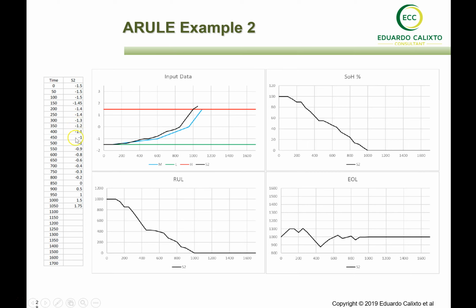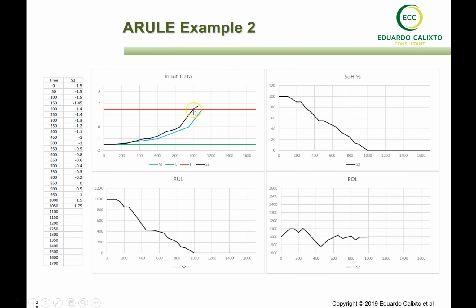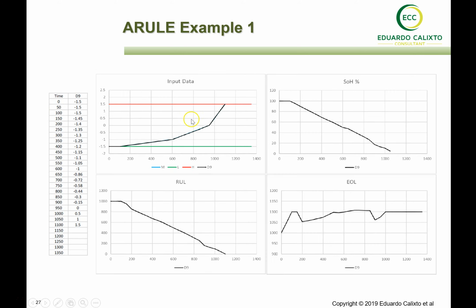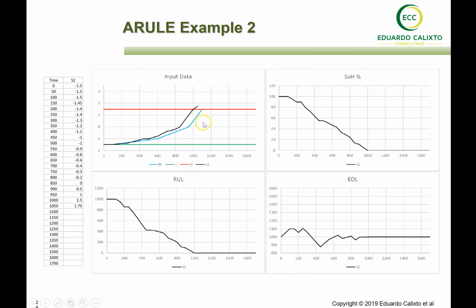As long as you're starting to input the points, this profile starts to modify and demonstrate to you that you have an expected life not only 1,100, but now you have 1,000. So before you expected. If you are able to get such information, such prediction, you are able to anticipate that the failure will occur before it is expected, and then of course, you can do a preventive maintenance at 1,000 or a little bit before 1,100. You do it around 1,000, and then you avoid the equipment shutdown, and that is the information that prognostic health management gives to you.